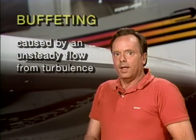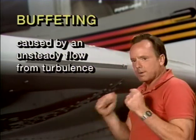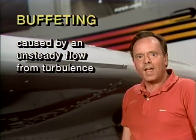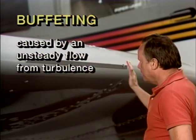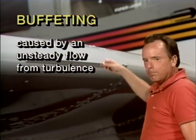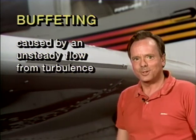Now they ask you some questions on buffeting, and buffeting occurs, by the way, sometimes when you're in a stall, and what it is, is a banging on the aircraft. And they want you to know it's what's called the intermittent application of forces to a part of the airplane caused by unsteady flow from turbulence. So when you're stalling an airplane, you're actually creating turbulence, and then you have buffeting on the aircraft, and it's the intermittent application of forces on the aircraft.